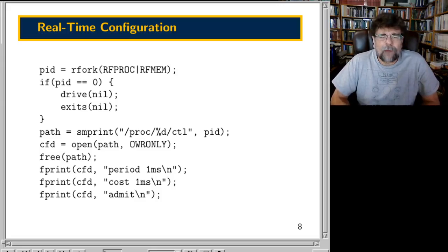However, those environments are ones where there's enough persistence that you can kind of get away with a little bit slower than you can with these LEDs. It becomes very noticeable that there is a blinking effect going on at 30 frames a second. So 60 frames a second is pretty much necessary here.